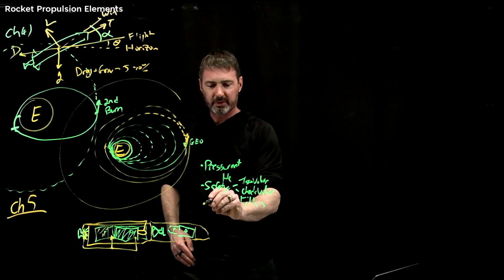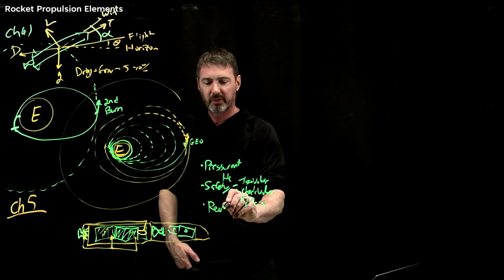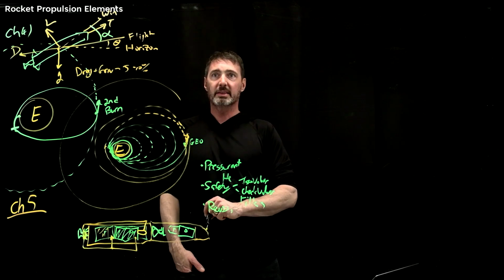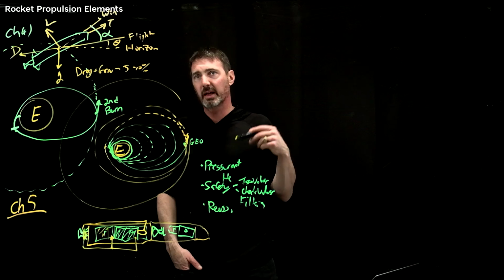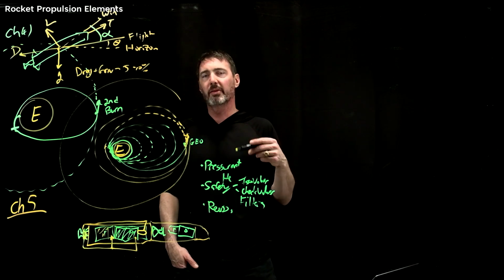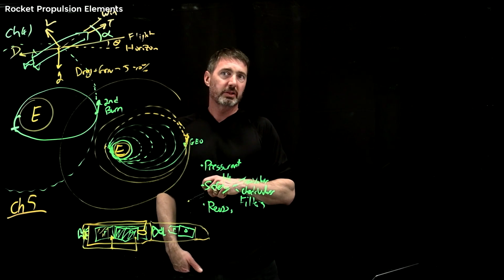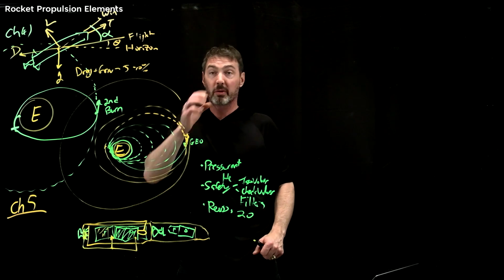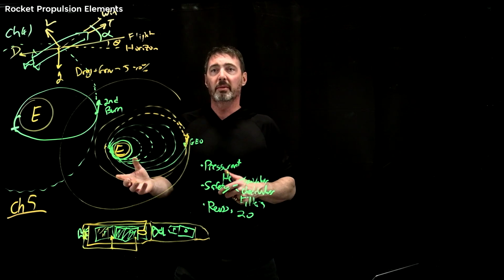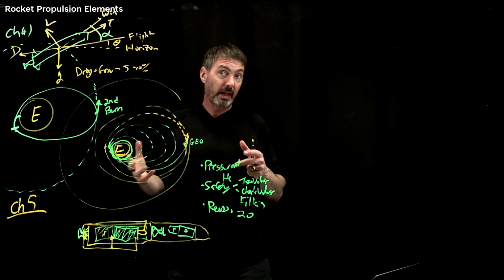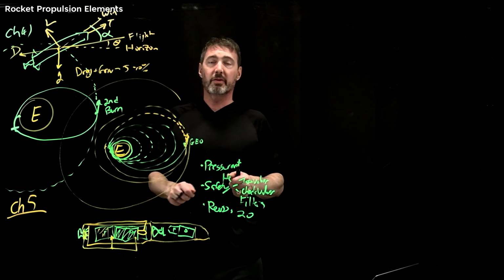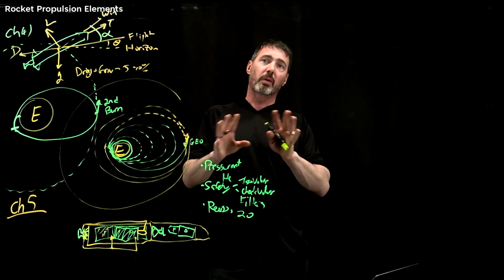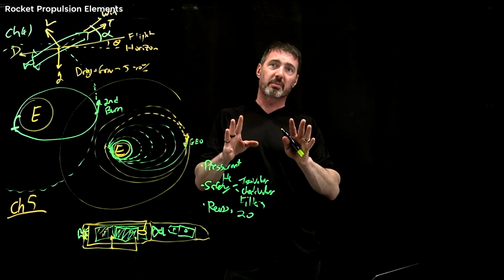If you're SpaceX and you're trying to do reuse, boy, a lot gets into that in terms of reuse. Usually it's the engine cycles that drive the reuse. So how many reuses? On a normal rocket engine, you would actually do, say, 20 reuses. And what that will let you do is build the engine. You may do 5 to 10 tests to tune the engine. Every engine flow path is a little bit different, so you are tuning to get that right O to F in terms of the highest performance.